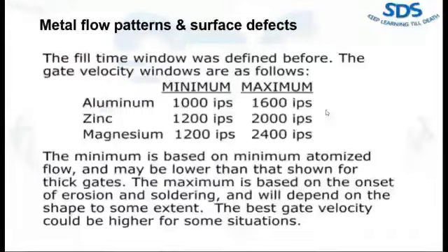We are talking about the gate velocity. Why 35 and why 50? There is some logic to taking this gate velocity, because we need some casting pressure, because we are doing high pressure die casting. We are not doing gravity casting or low pressure casting or other casting. If we are talking about high pressure die casting, what are we talking about? High casting pressure.